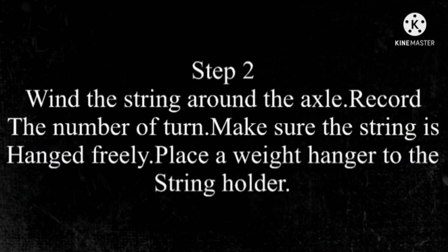For step 2, wind the string around the axle, record the number of turns, and make sure the string hangs freely. Place a weight hanger on the string holder.